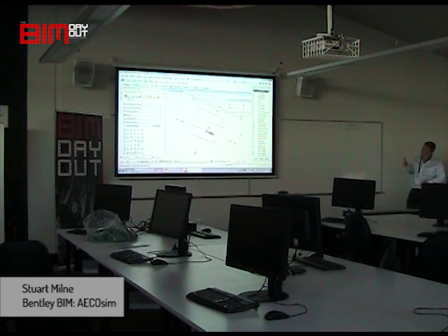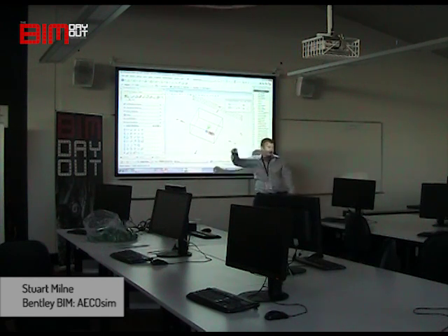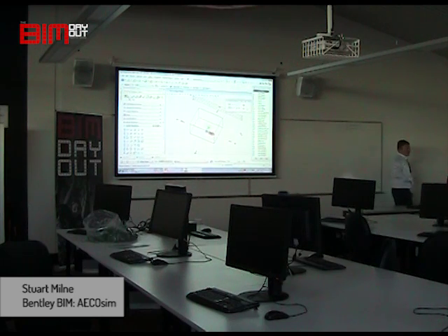Excellent. Now, what we've done is we've made the active transparency of any further elements we create 90. You can see it up there, it still says 90%. So before we go and do the next task, which we actually don't want to be transparent, let's go back and set our active transparency here to 0. Because all further elements we create would be 90%.